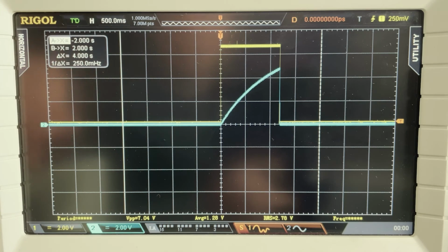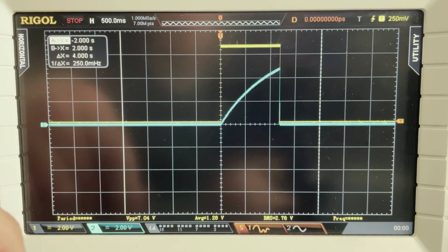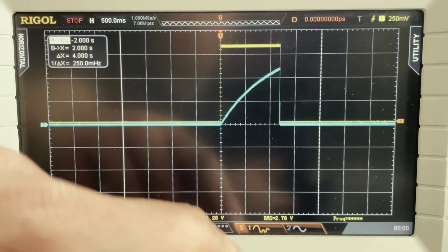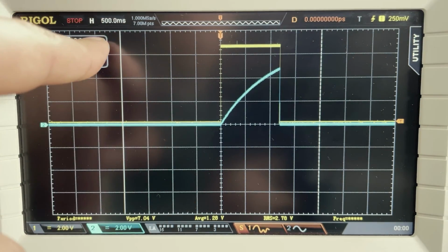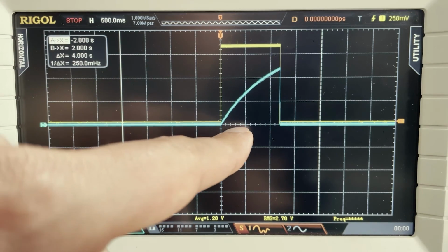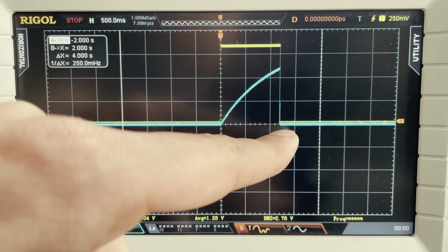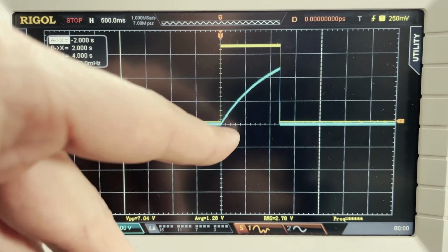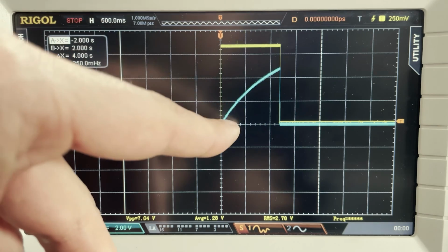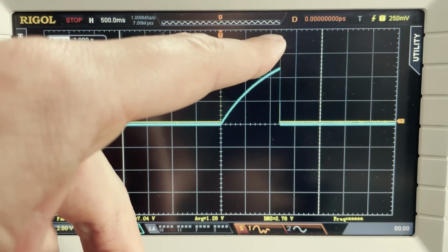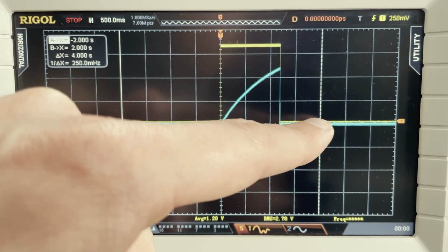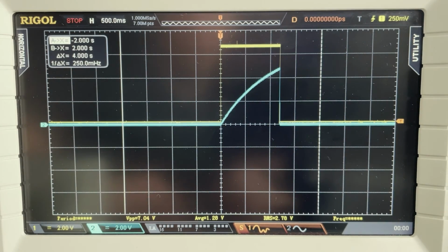All right, since we had a 100 microfarad capacitor and a 10,000 ohm resistor, we were expecting about 1.2 seconds. So as we look here, we have our 500 milliseconds per division. So we got half second, 1 second, and then yeah, we're at about 1.2 seconds. So this is exactly what we expected. Our output goes high, and then as we hit 2/3 VCC, the whole thing just resets, drops, and keeps on going. And if I push it again, we'll see if it triggers again.